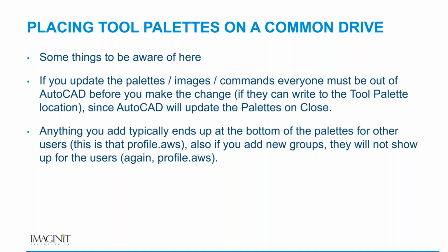One of the things that I tell people when they're implementing tool palettes is try to do everything that you can first, and then if you do need to add things later, either warn your users that it's going to be at the bottom of the palette and they have to drag it up.